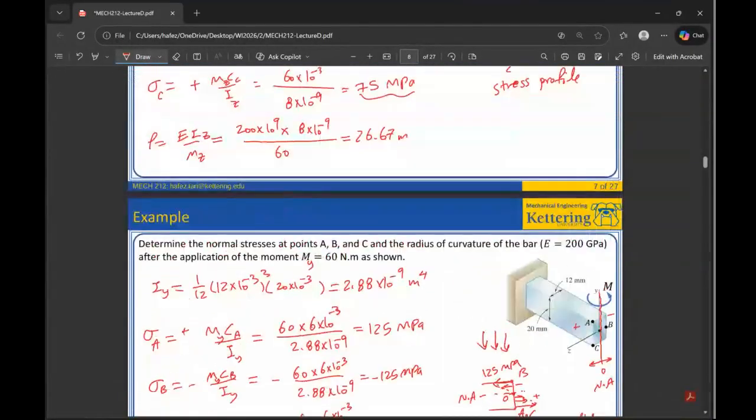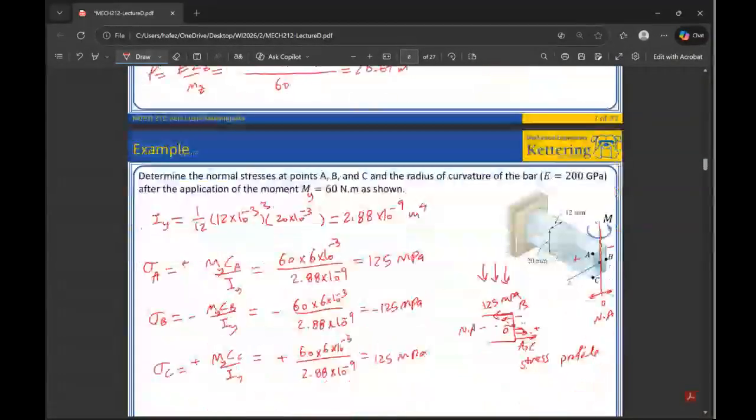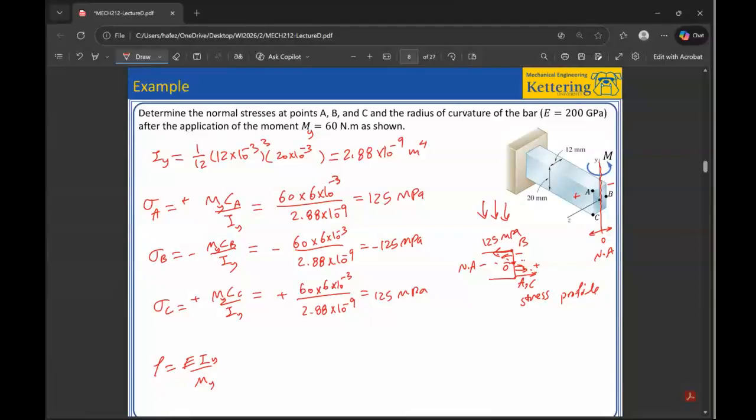So that was the reason I said in buildings you would get to see components oriented this way, and the load is coming either top or bottom like this. You're bending it upward, whether it goes up or down is the same thing. But if you lay your beam like this and you load it sideways, as if you're putting the beam like this, and then you're loading it downward. So the better one is the first one because it gets less stressed. As an engineer, we should be mindful of that. That's the lesson.